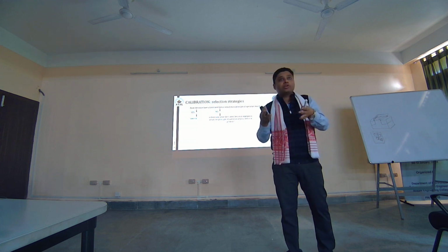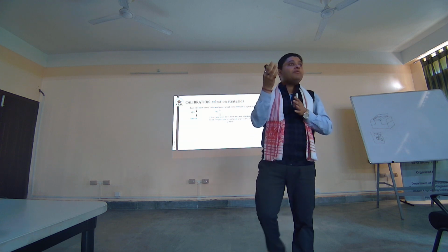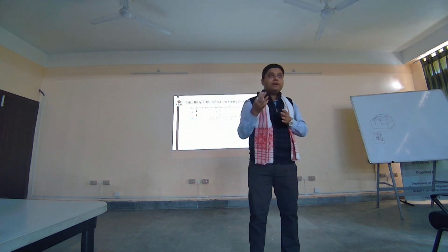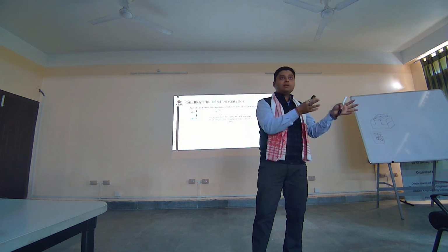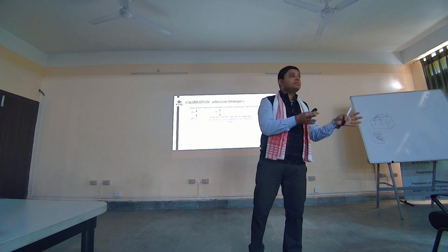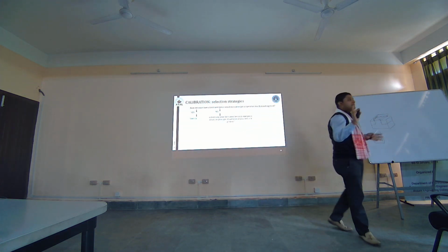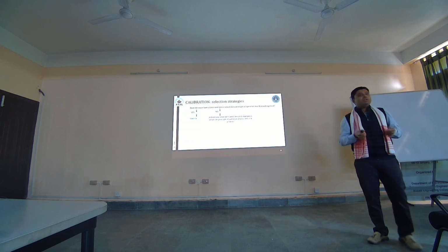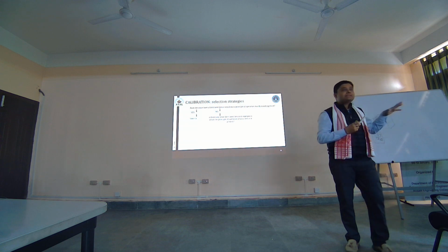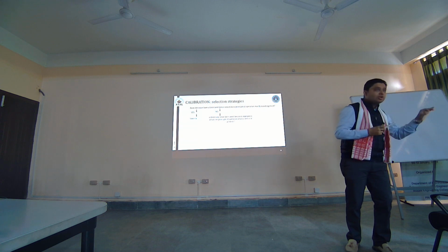So in that case, what are you going to do? You have to see whether the principle of operation of your device, in FinFET it is also drift diffusion, matches with your MOSFETs, right? Then you have to select the MOSFET itself. So are you getting my point? If a similar device is already fabricated, you have no issue. You directly pick that up and do it. But if you have a device where you do not find any exact match, you will go to the next level.